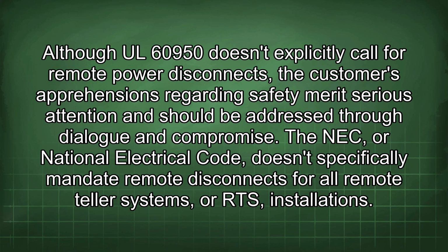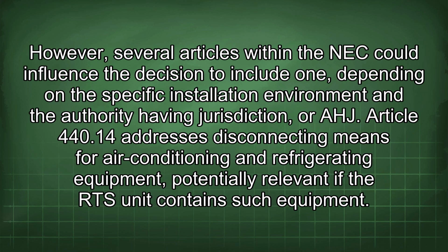The NEC, or National Electrical Code, doesn't specifically mandate remote disconnects for all remote tower systems or RTS installations. However, several articles within the NEC could influence the decision to include one, depending on the specific installation environment and the authority having jurisdiction, or AHJ.